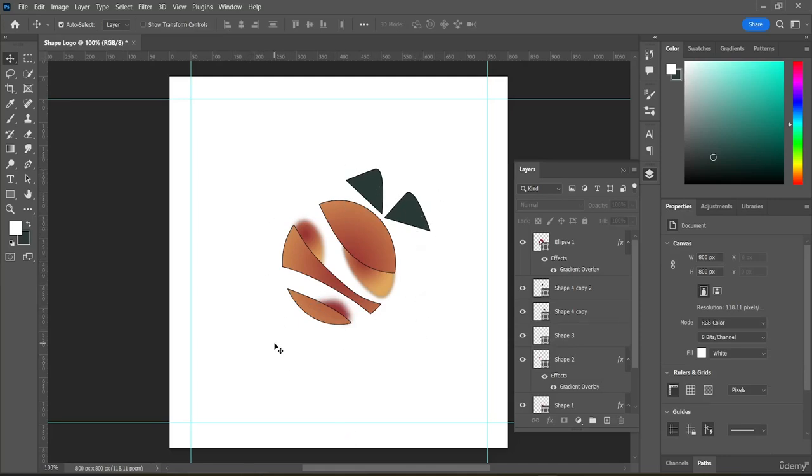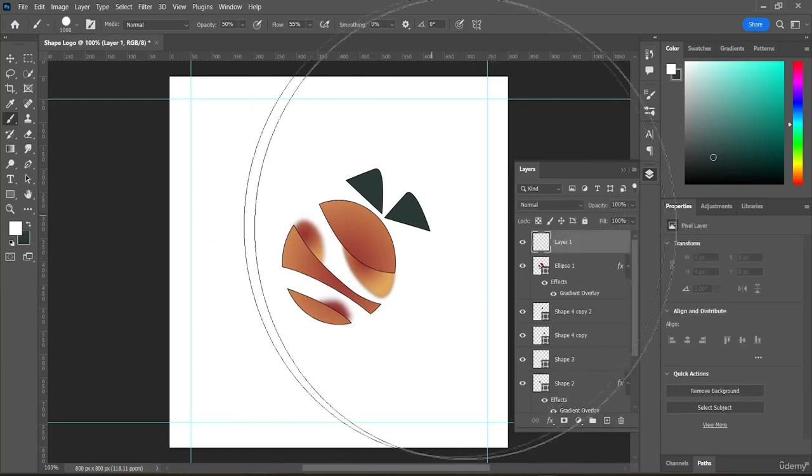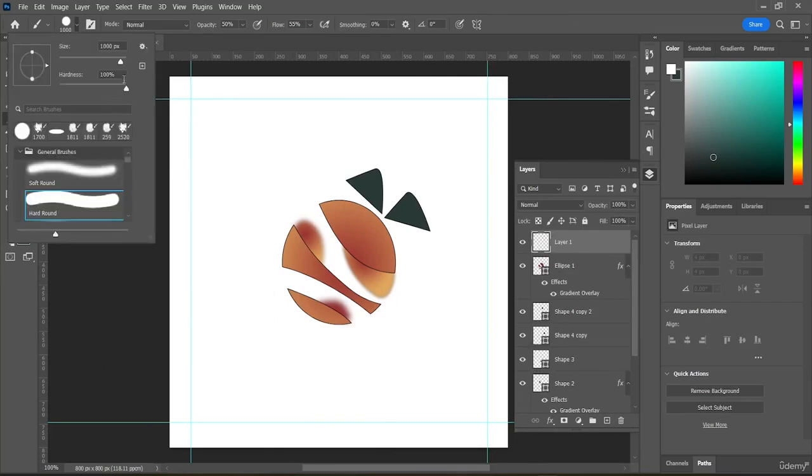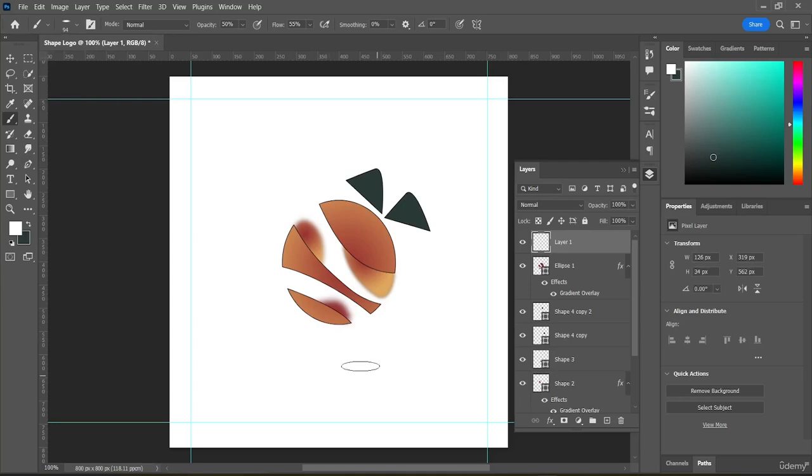If you do want to put some shadows, in that case, you need to come here and choose your brush tool. And after taking the brush tool, right over here, let me just take a new layer. Okay, so I'll just take a new layer and let me just decrease the size of my brush, which is around this. And let me just select what is going to be the width as well. Okay, so over here now let me just increase the size a little bit, and also I will just decrease the hardness to 50.